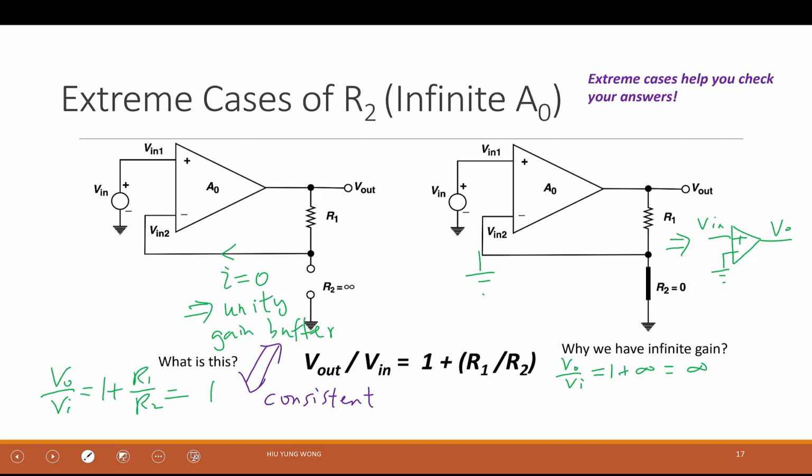Now another thing to check your answer in the exam is to check the unit. I asked you for the gain. What is the unit of the voltage gain? Voltage divided by voltage. Unitless, right? And if you came up with an expression that has R0 or gm alone, then you know you are wrong. But if you get gm R0, you know you might be right because it's unitless. Ohm times 1 over ohm, right? So try to have this practice, okay?